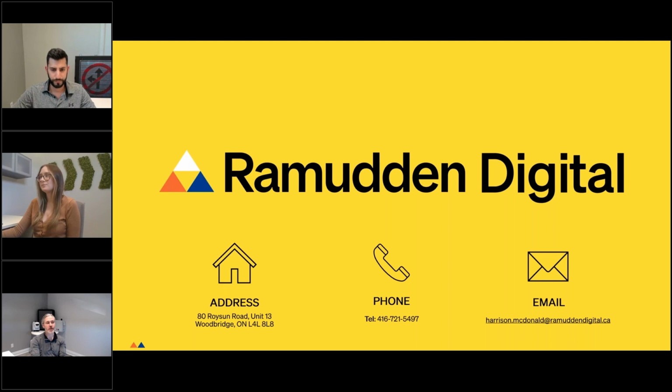But in our experience, we've seen the traditional LED blankout signs used in that fashion across standard signal arms in Toronto and in the New York region. So we anticipate it won't be a major issue with typical traffic poles that are used, but it's going to vary based on what you have and the specs of your poles. But certainly if it's on the vertical portion, no problem. Once you start getting way out towards the signal head itself, I would definitely do an analysis of the static load and the wind loading based on your pole specifications.